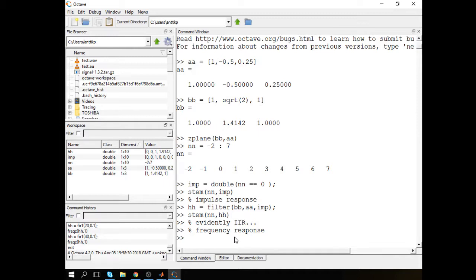But if you design a filter, it's actually a very practical thing. If you don't know the frequency range where you are using that filter, then how much do you know about this system at all? So the fundamental thing, you need to know the sample rate.